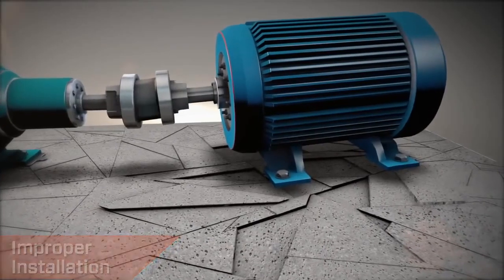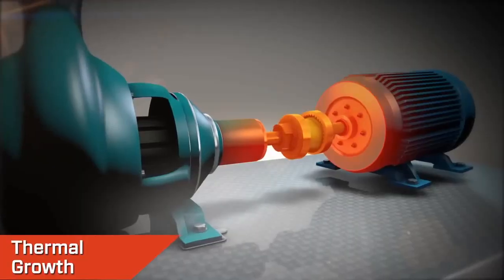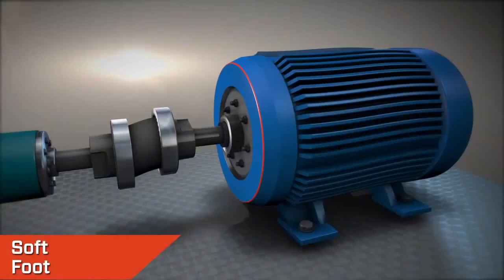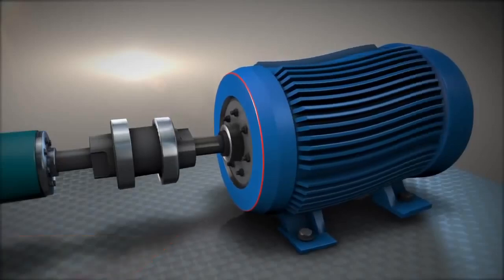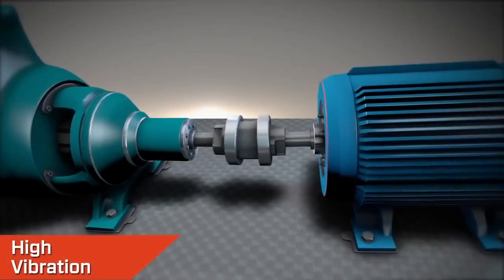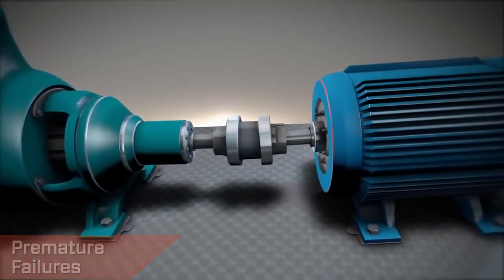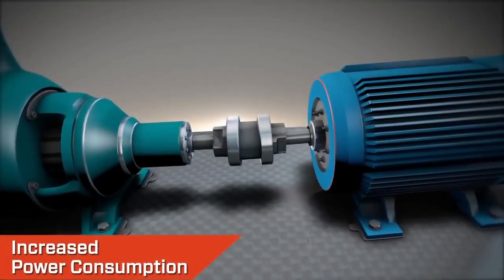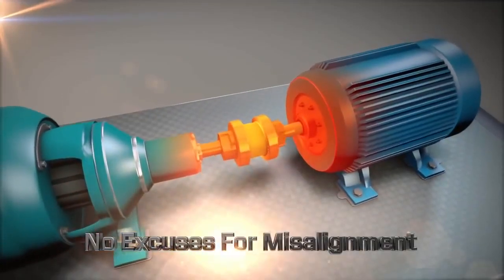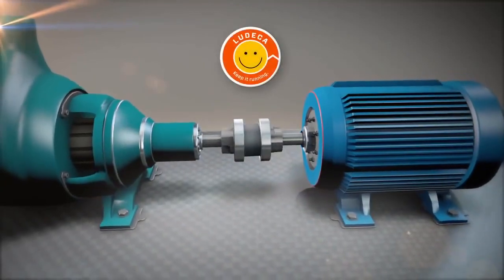Improper installation, foundation issues, failing to account for thermal growth, pipe stress, load stresses, soft foot or machine frame distortion. The effects of misalignment are high vibration, premature equipment failures, increased power consumption, and reduced production. There's no excuse to let misalignment cost you money. Protect your machines and minimize costly downtime with precision laser shaft alignment.